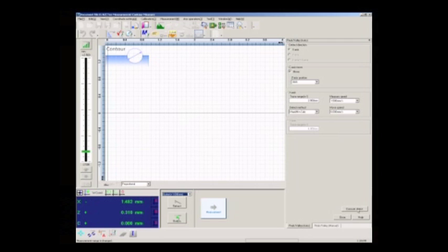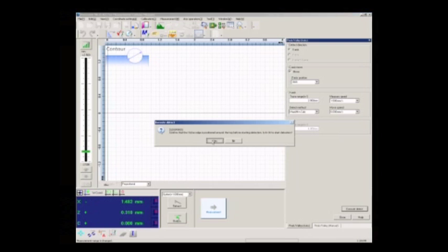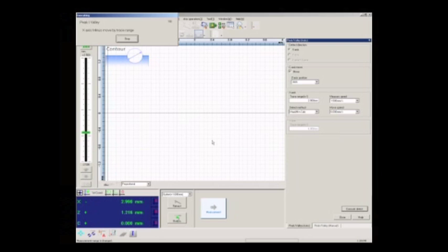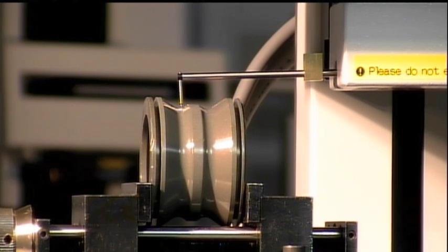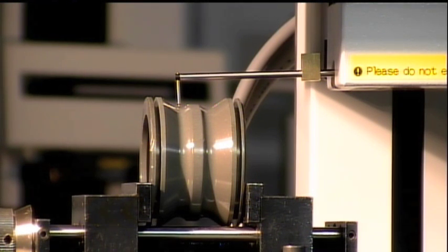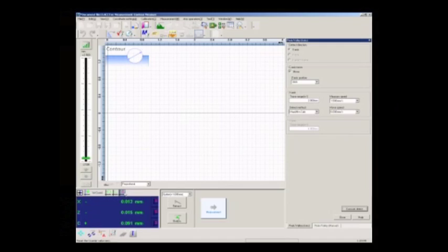So when we execute this, the stylus will actually pass through the valley. Okay, so the stylus is actually moving. Yep. Okay, I see it. It's coming down, it's hitting the valley. And then it automatically locates what the lowest spot is? That's right. Now all that movement's done, and it moved the column to put us at 90% of the probe range. So now what I want to do is call this my origin. I'm going to zero out my scales down here, and now that's our origin for the part. So everything is referenced from there from now on.